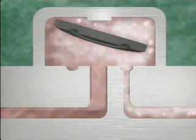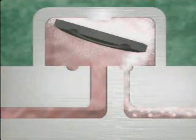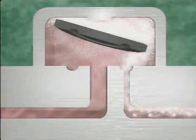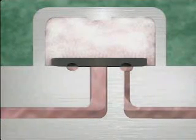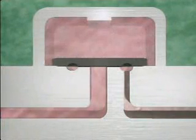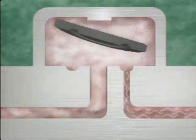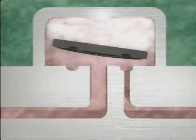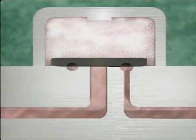At the same time, flashing condensate flows out and causes a pressure buildup in the area above the disc. When sufficient pressure builds up here, while pressure on the underside of the disc has been reduced, the disc is forced down onto the seating surfaces, which closes the trap. The disc is held closed by the pressure of the steam that's in the chamber above the disc. When this steam condenses, changing to a liquid state, and the pressure above the disc becomes low enough, the disc rises and condensate flows out, until velocity and pressure conditions within the trap again cause the disc to snap down on the seating surfaces, closing the trap.